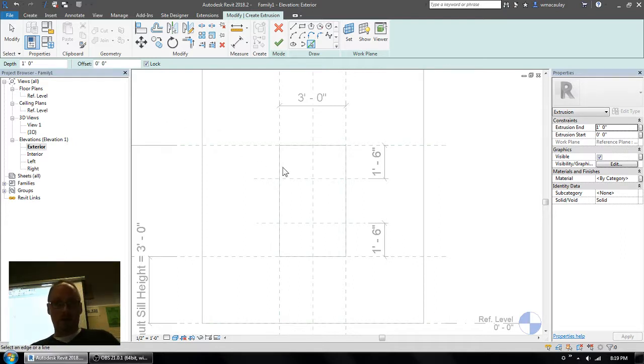So what I'm going to do is put my cursor over this one edge here. Now if I were just to click, I'd get this locked at this edge. Instead, I'm going to hit the tab key once, twice, 3 times, and you can see all 4 edges are highlighted. I haven't even left clicked yet, so this is hover, tab, click. Grab the pick tool, make sure lock is enabled, hover without left clicking, tab, tab, tab. And now, click. That's what you should get.